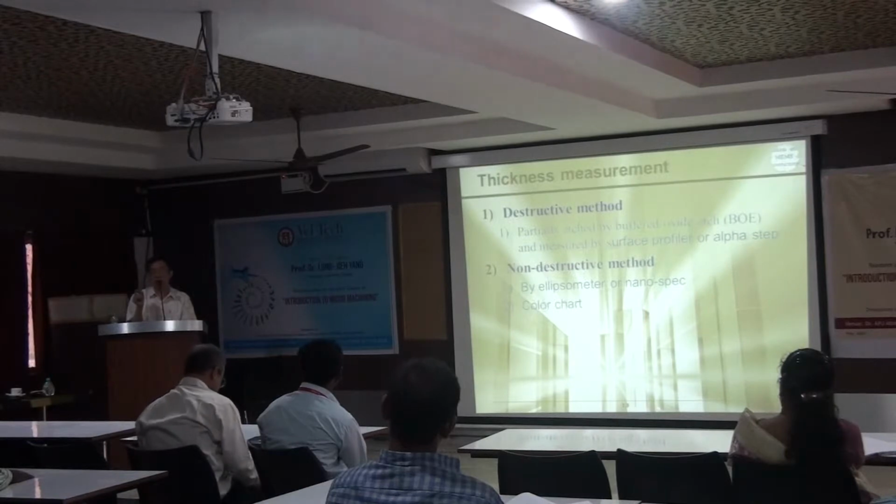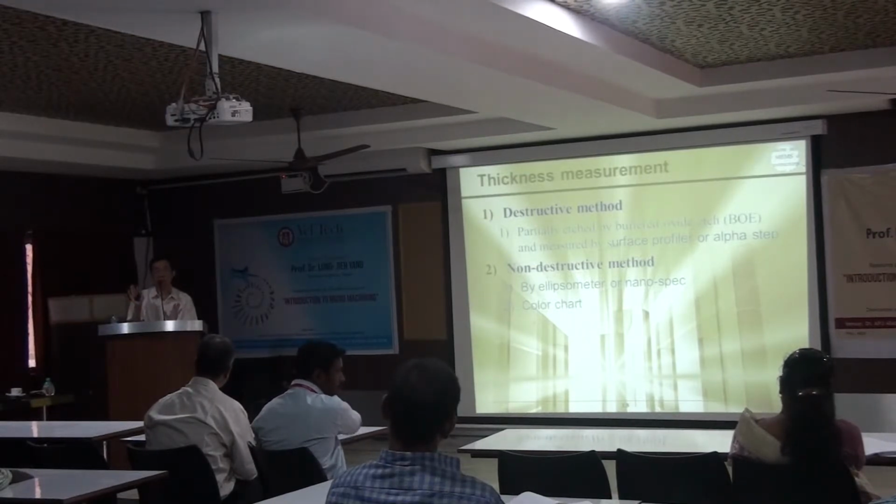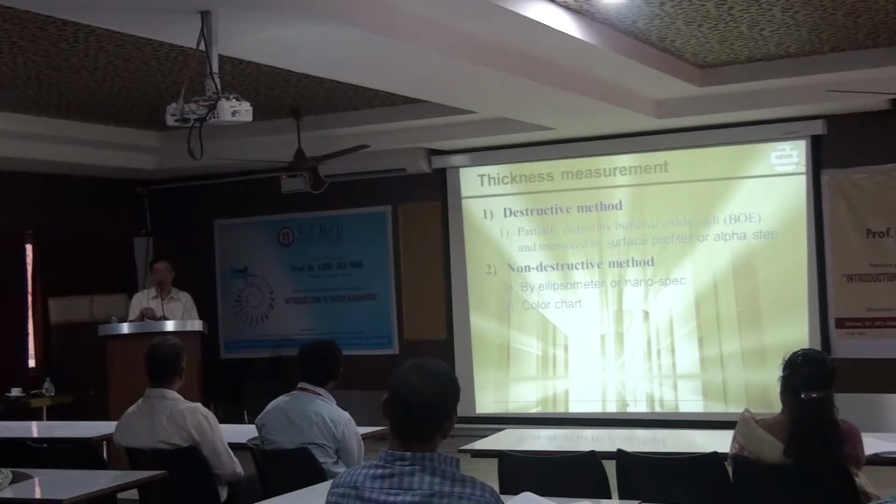But if your oxide thickness is more than 1 micron, for example 1.5, it will become transparent once again. So your wafer will turn back to a gray color. Because it is very thick, it is something like glass, very similar to glass.